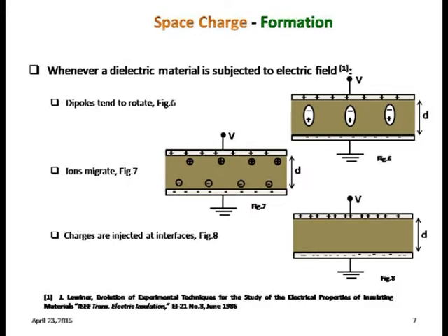But these interfacial charges are formed ideally. When practical insulation is there, if there are some ions inside the insulating material, they tend to get attracted like this, in the opposite way. So in this case, at the interface you will have positive charge, and immediately next to it you will observe some negative charge, but these have been observed never to combine with each other.